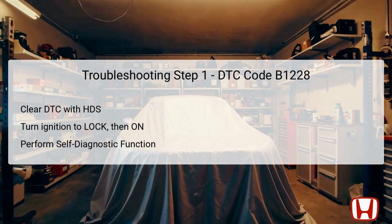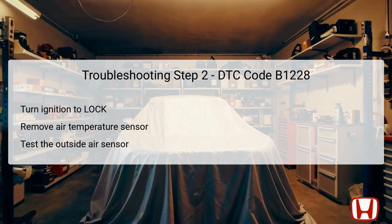If not, you may be dealing with an intermittent failure, necessitating a check for loose wires or poor connections. Next, turn the ignition switch back to lock before proceeding with the disassembly required in this step. Remove the outside air temperature sensor carefully. This sensor can usually be accessed with appropriate tools and is often clipped into a bracket or held in place with screws.